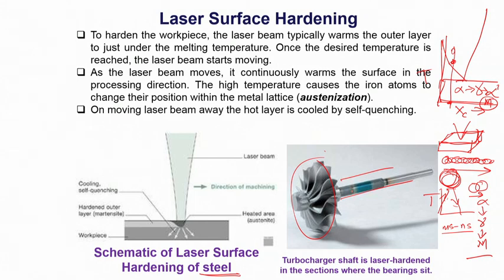Conventionally, you charge the whole component inside the furnace. Now you unnecessarily heat the entire volume, which you don't need to heat. And then when you subsequently quench the whole component, there will be scope for a lot of distortion or bending or undue oxidation, discoloration and so on.